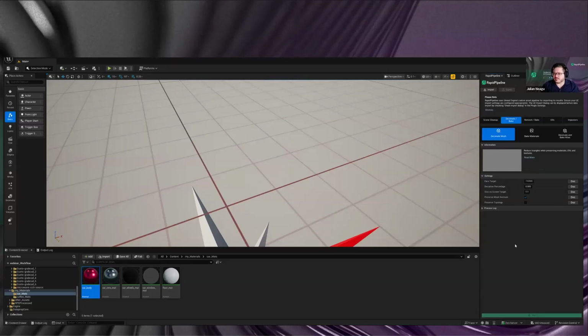But from our testing, our decimator is a bit more adaptive compared to other decimators and is able to go way more down in the resolution while keeping intricate details like little holes, for example, a lot better and not collapsing those compared to other decimators on the market right now. And yeah, a few additional flags, basically topology preservation. And what we have on the decimator as well is a deviation target, which is very interesting.